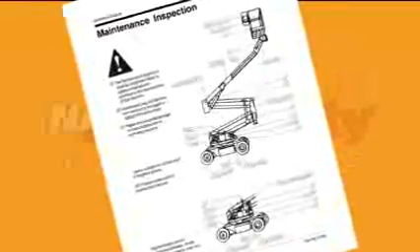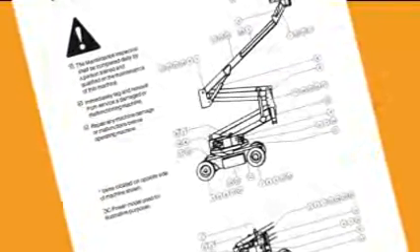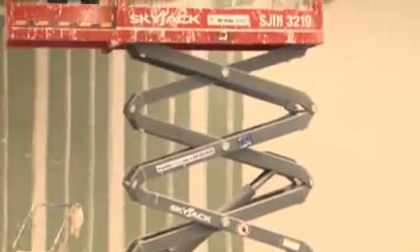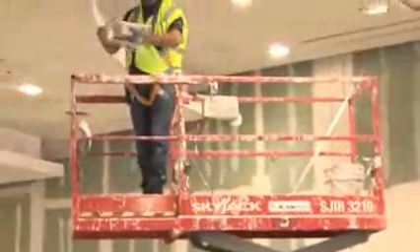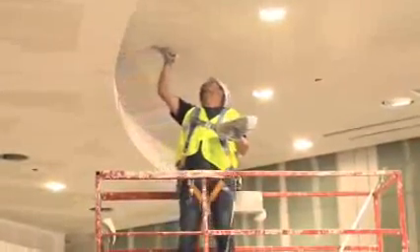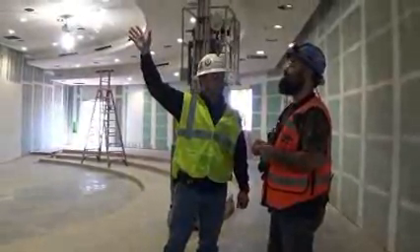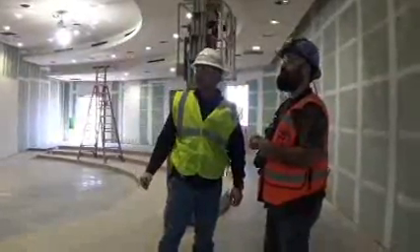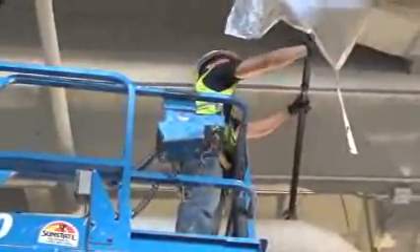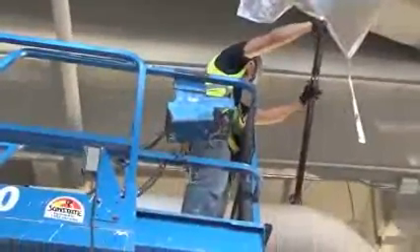A preventative maintenance program based on the manufacturer's recommendations must be established. It must be performed on a timely basis and take into account the workplace environment and the severity of use of the MEWP. Any malfunction or problem identified which affects safe operation must be corrected by a qualified person and authorized by the owner before the MEWP is returned to service.